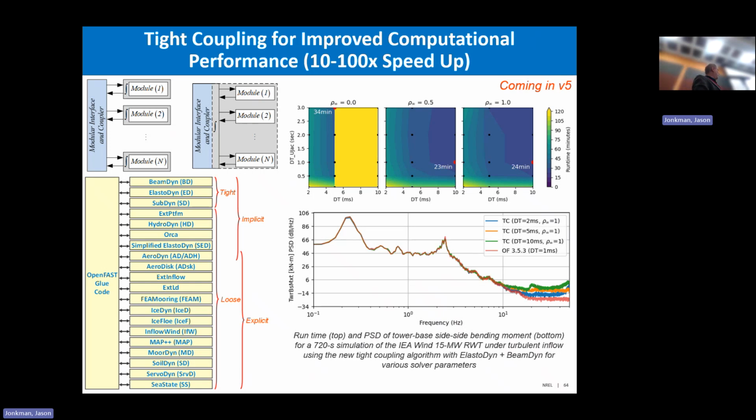Which ones are loosely coupled here in 5.0? Which ones are now tightly coupled? This also clarifies which ones have explicit and implicit coupling. All the explicit modules that are loose get staggered in series; we just serially connect them together. Everything tight gets put in a big generalized alpha solve, and everything implicit basically gets put in one big Jacobian that we ensure is consistent every time step.